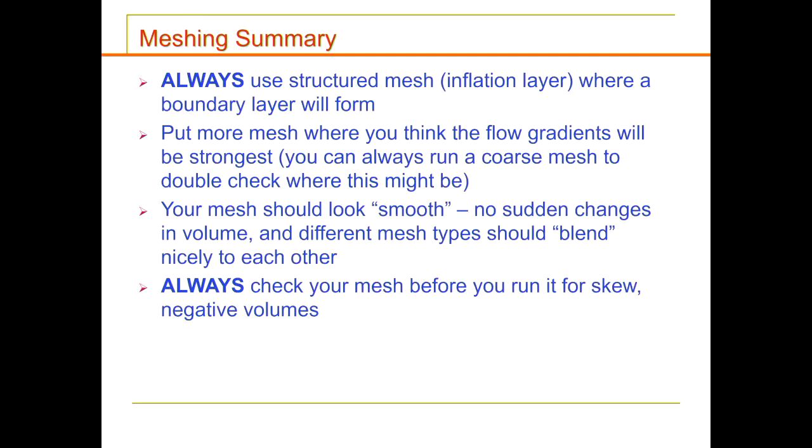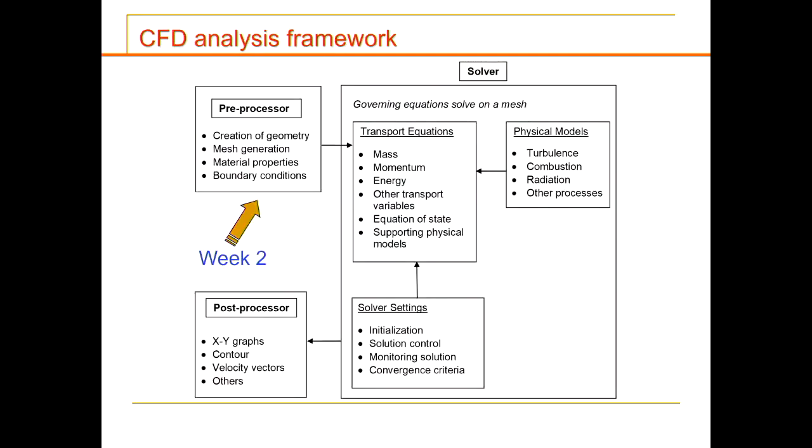That's why CFD is not a straightforward process. You need to do it iteratively: run the solution, check your solution, validate. Even if it is good, you still need to do a few more tests to get to where you want. It's an iterative process.